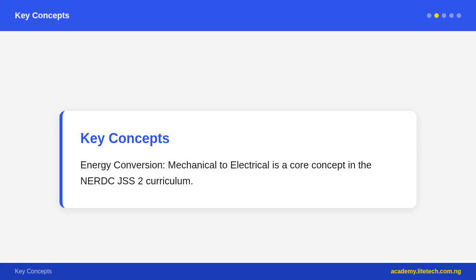In a generator, coils of conducting wire are wound on a rotating part called the rotor or armature. The rotor is placed inside a strong magnetic field, usually provided by permanent magnets or electromagnets. When an external mechanical force rotates the armature, turning it round and round, the wire coils continuously cut through the magnetic field lines. This induces a voltage in the coils, which drives an electric current through the external circuit.